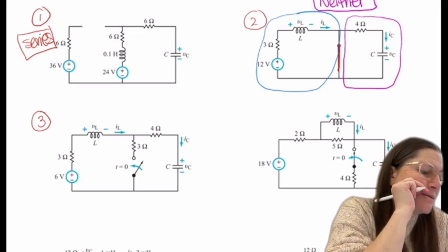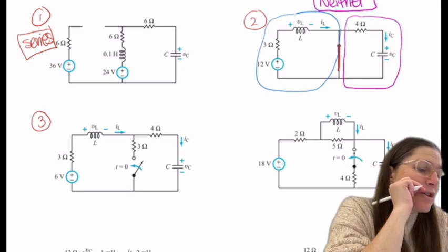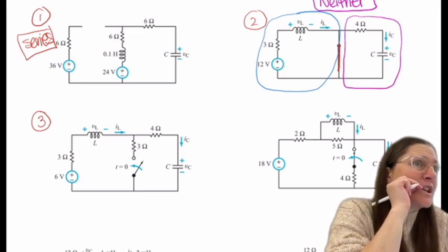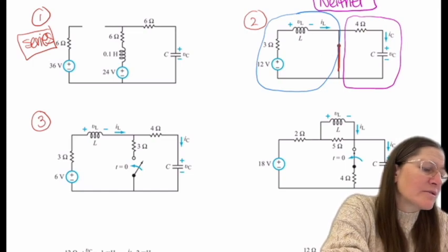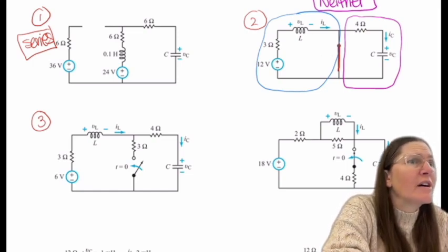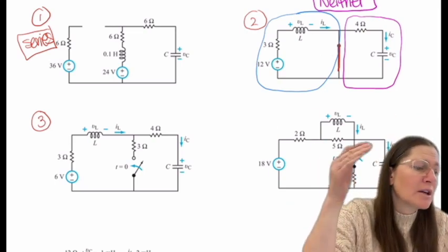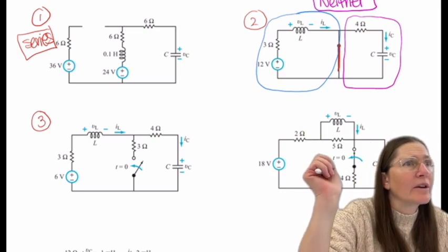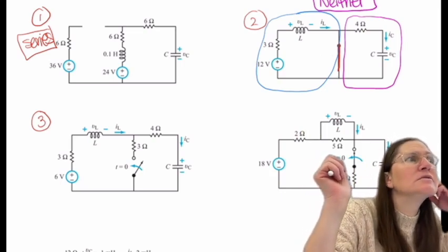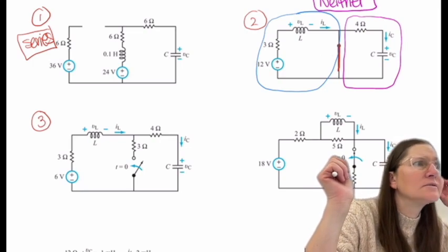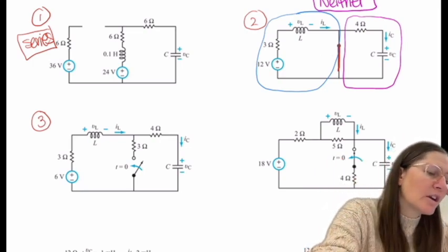All right, this one. Oh, yes, Marley. At the final, why would we need to solve for the RC side? Because there's no sources over there. So for the final one, VC would be 0. But initially, you're going to have a voltage across it of 12 volts. Oh, okay. So you would still do your final plus initial minus final, e to the minus t over tau. And then tau would be 4 times C value. The capacitor still discharges, and we might build off that circuit in such a way we need to know how it does.